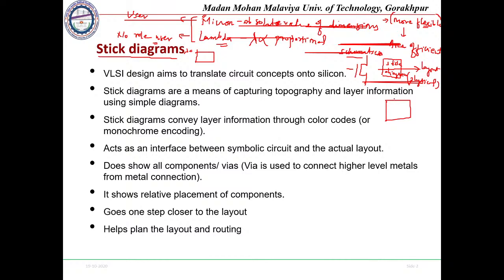Okay, in that different layers, one contact and poly, different layers are there, that might be a complex circuit to design, a complex physical layout design. So to simplify this layout, we do an exercise that is called stick diagram. Here what it will do is, it will give you the information, like if it is an NMOS, a poly will be there. Each layer will be represented by a line. So to simplify the layer information of a particular layout, we will be drawing the stick diagram.